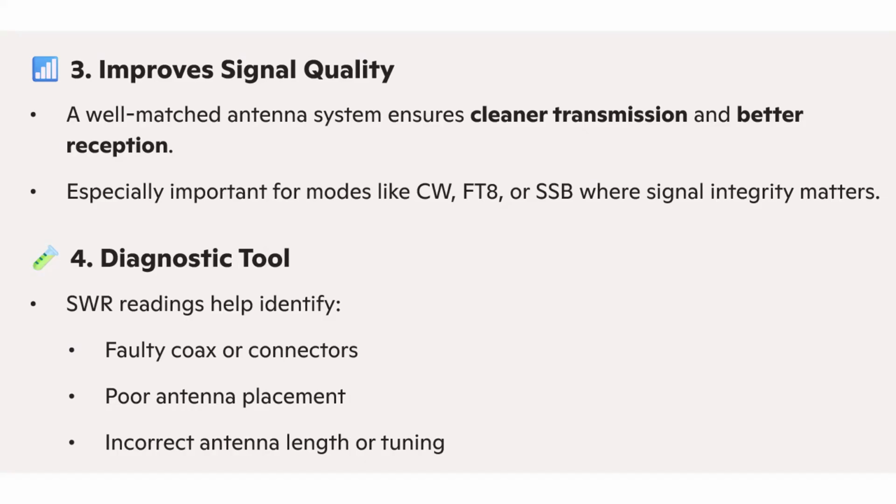An antenna analyzer, through SWR readings and other things, can help you diagnose your system if it doesn't seem to be working right, to find faulty coax, connectors, maybe poor antenna placement, or incorrect antenna length or tuning.